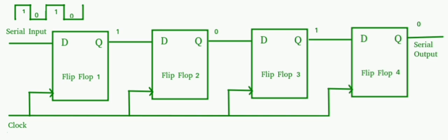The difference between Moore machine and Mealy machine, which are both finite state machines. Moore machine, the output is a function of the present state only. Mealy machine, the output is a function of the present state as well as the present input. In Moore, the change in input does not affect the output of the circuit. In Mealy, the change in input may affect the output of the circuit.